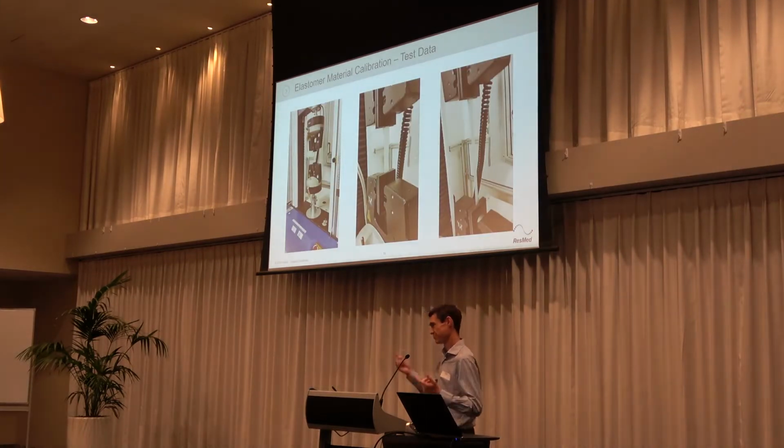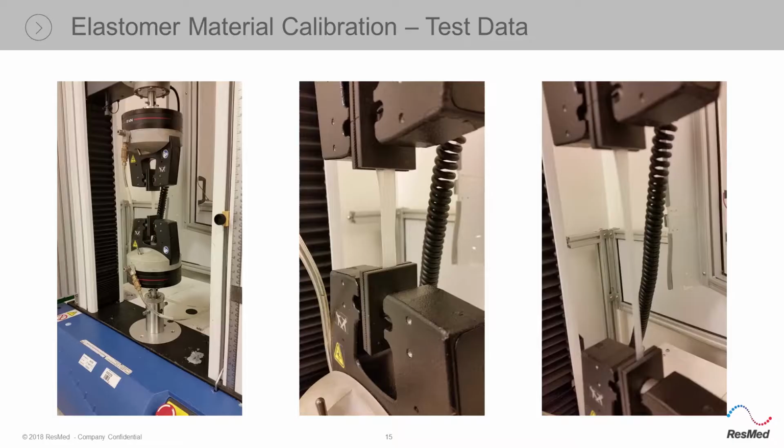We just cut the headgear into bits, a bit that was close enough to straight, but it wasn't good enough to say that it was a uniaxial test specimen. The actual profile blends and changes, and we've got all sorts of subtle changes on this, which meant we couldn't just say, here's the area, force over area is stress. That wouldn't work. So we mimicked the geometry and the test in the FEA model.